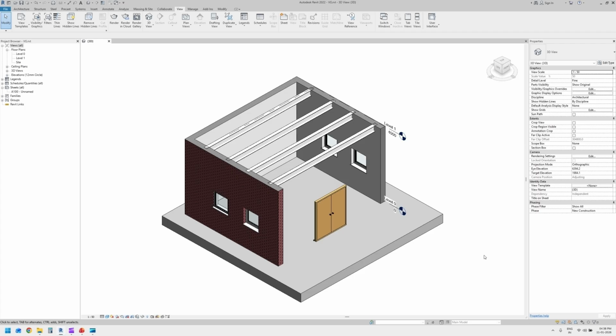In this scenario, three walls are turned on, but one wall is missing. If you check and find that the category and subcategory are turned on, but the wall is still not visible, then you should click Reveal Hidden Items. This tool should be your best friend.